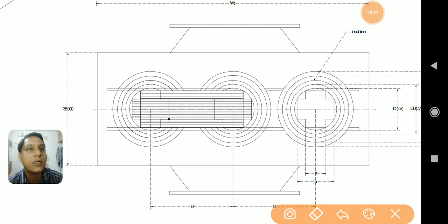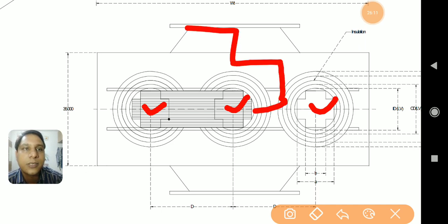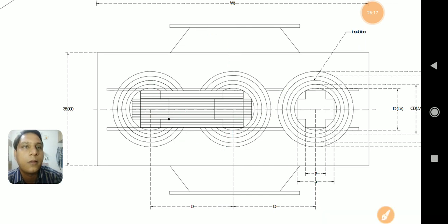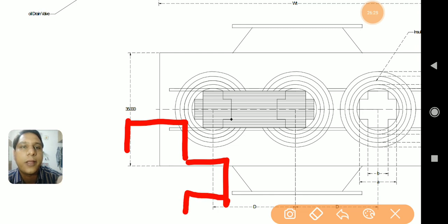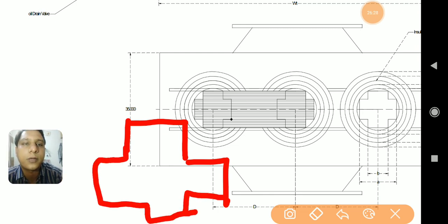First of all, the 3-phase winding is there, so 3 limbs are there. We know all the 3 limbs, and we can represent them as core number 1, 2 and 3. As we know, for this transformer, when you go through the design part, you will understand that a 2-step core is used, whose shape is represented here like this. The shape of the core, if I look at it, you can easily identify the 2-step core part.